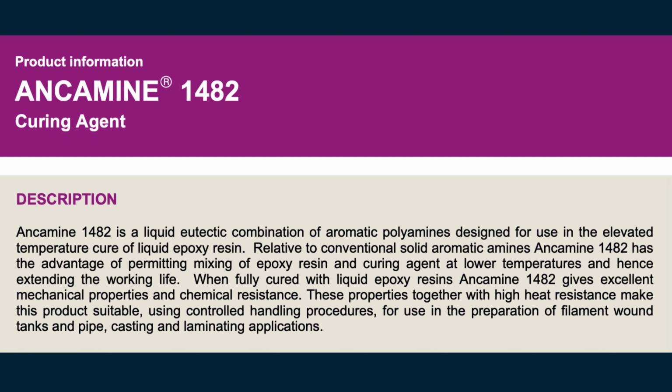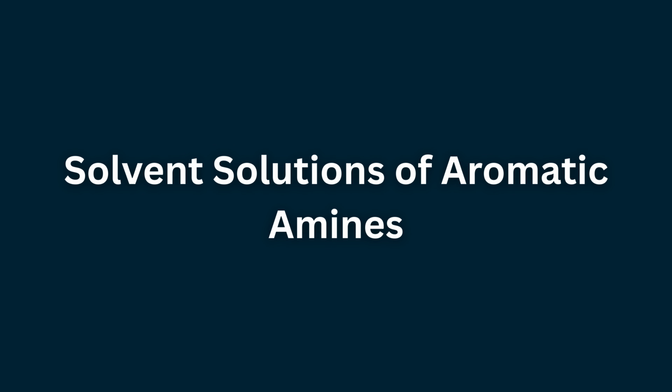Although these eutectic mixtures may crystallize during storage, they can be easily returned to the liquid state by heating to about 40 degrees Celsius with stirring. This process does not affect their curing behavior or the properties of the final cured epoxy.